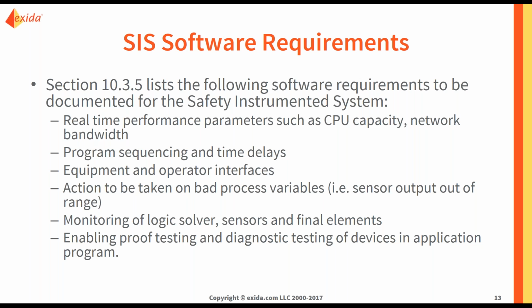It includes equipment and operator interfaces, actions to be taken on bad process variables, so if your sensor output is out of range. It includes monitoring of the logic solver, so if the logic solver is able to self-monitor, and then if it's able to monitor the sensors and the final elements. And then enabling proof testing and diagnostic testing of devices in the application program. So again, this is a high-level look. This does not encompass all of the requirements in the standard, but it is a good summary of the software requirements for the SIS.